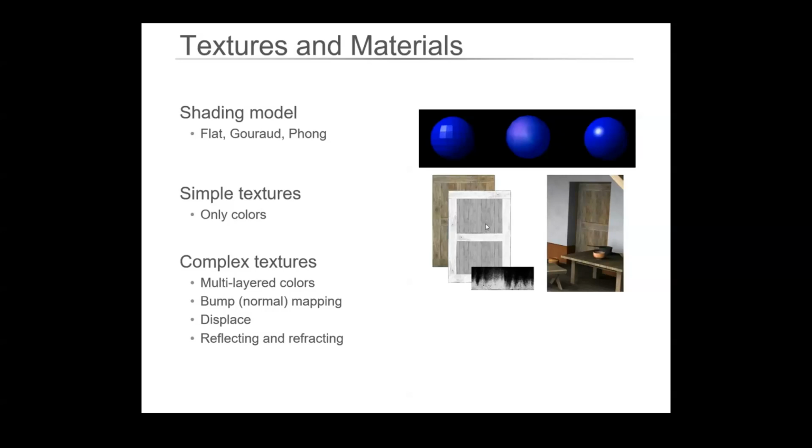So it will generally come out flat. Even in this instance here, a timber door, you would only get the look of the joints as a photographic thing, whereas you can get into more complex profiles and textures where you have bump mapping and displacement and alpha channels, which overlay a whole lot more information and make it look more realistic. So those joints would look like they've got some depth rather than just being a change in color in a photograph.